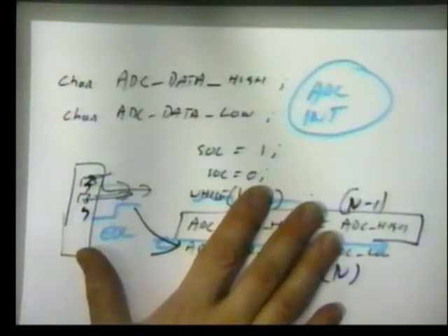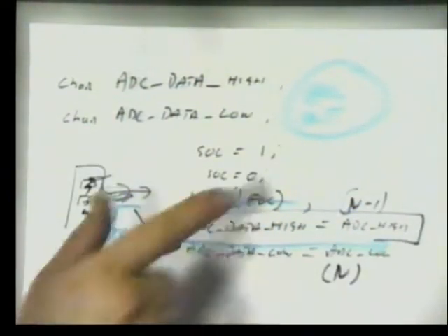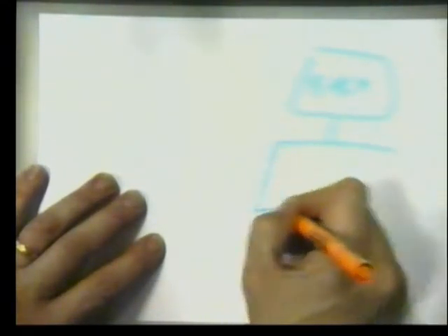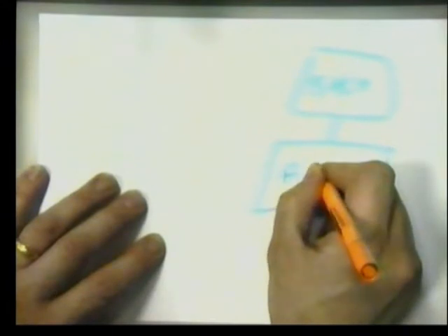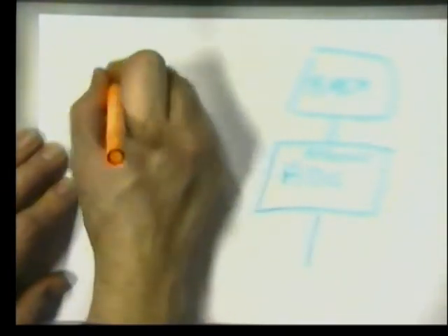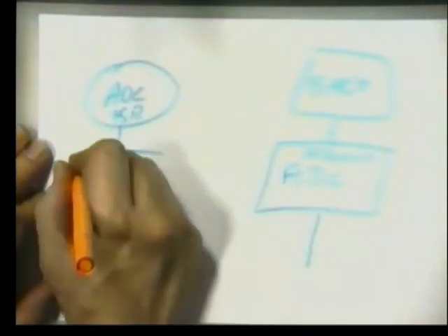You have to create separate entities, separate data areas for each independent routine. So the structure I've just drawn here for polling, that would work, but for interrupts it won't, because you never know when an interrupt will occur. What you must do is have separate memory locations. So here we have our background process, and it's got to process ADC data, and then move on, and here is our ADC interrupt, our interrupt service routine.